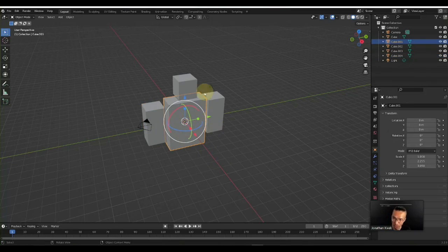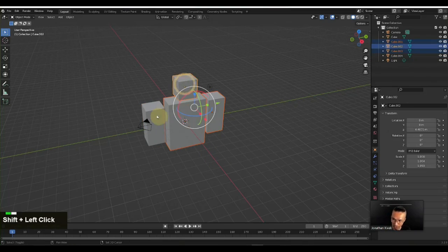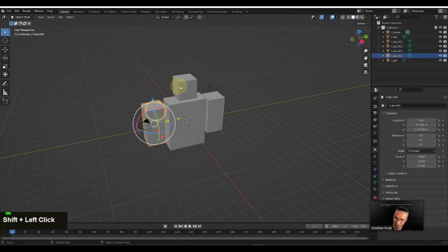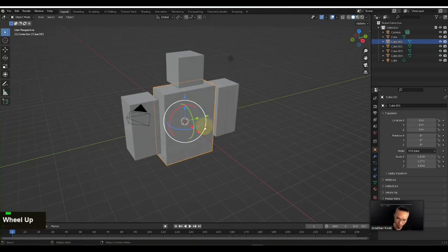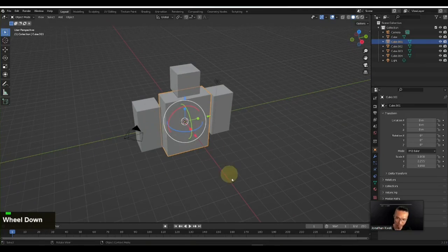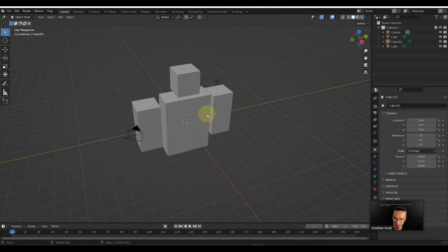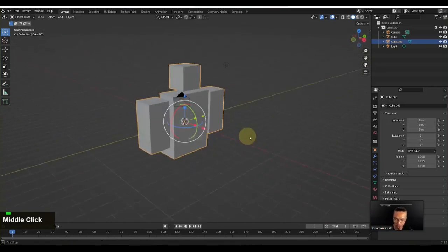So what we'll do is we will select all these meshes, and you want to select the mesh that you want to use the pivot for to be the last. So we're going to select all of these, and then hit Control J. Then they're basically going to merge all the mesh into one. So we're in object mode, we use Control J to merge all these different shapes into one.